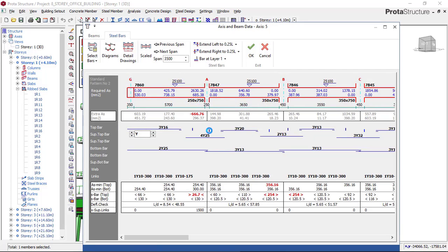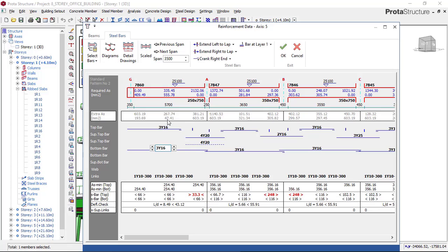So now, just click on this okay, and go ahead and click once it's done, then start changing my bars, numbers of bars, and all that. Like I said before, I would take this to be 20, and then increase this to 3 numbers. If I use 3 numbers of 20, then this will be okay. Okay, this is still lower than 75, so I'll go and do this. Most people accept that, but me, I don't accept that. I like to have my area of steel to be at least lower than 70, not higher than 75. This is also not okay because this is showing 47.